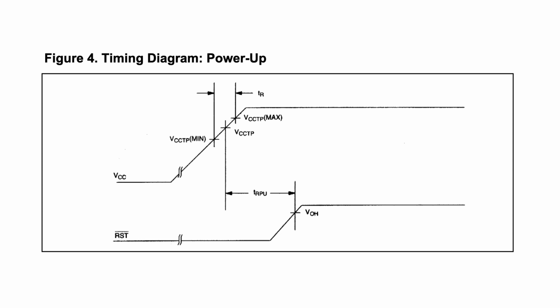So zooming in on the power-up timing diagram from the DS1813 datasheet, notice how the reset line is held low until VCC reaches the threshold voltage, after which the 150 millisecond reset period begins. Now, it's only this initial power-on reset that I want to delay. All the other resets, triggered by the push button or maybe even by software, don't need any extra delay. I mean, the clock is definitely up and running when those events occur. So all I really need to do is delay the DS1813's VCC input reaching that threshold voltage, and that's really easy to do with just a simple RC circuit.